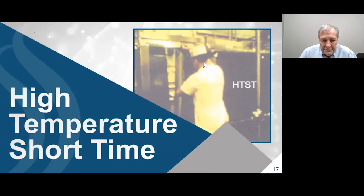This is a picture showing a high temperature short time. This particular gentleman is looking at the cooling section plates. And what happens when we have cracks and pinholes in the cooling section plates of a high temperature short time, we can have contamination from the glycol and sweet water. This is a very common situation. I've probably been in 100 dairy plants during my lifetime. At least 25 of them had issues with this particular type of contamination.